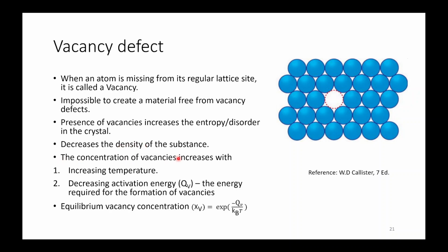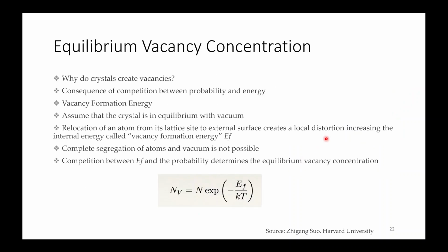The concentration of vacancies increases with increasing temperature. From this equation you can see that with increasing temperature there will be an increase in vacancy number, and if we decrease the activation energy QV, the energy required for formation of a vacancy, then vacancies will increase. This is the equilibrium vacancy concentration equation.